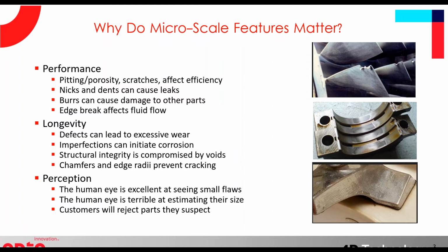There's also effects on lifetime of parts. Having defects can lead to excessive wear. They can initiate corrosion, and structural integrity can be compromised if there are voids in additive manufacturing processes or even in certain casting operations. And chamfers and edge radii are critical to prevent cracking, particularly in high stress surfaces.